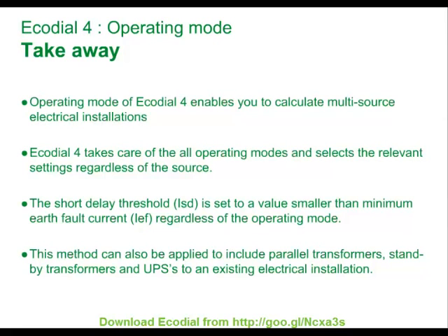Operating mode of Ecodial 4 enables you to calculate multi-source electrical installations. Ecodial 4 takes care of all the operating modes and selects the relevant settings regardless of the source. The short delay threshold, ISD, is set to a value smaller than the minimum earth fault current, regardless of the operating mode. This method can also be applied to include parallel transformers, standby transformers, and UPSs to an existing electrical installation.